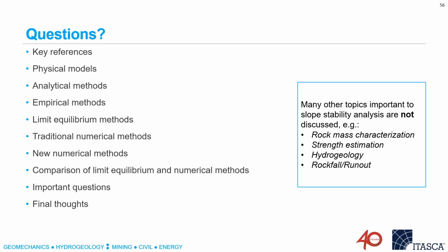And early work from Everett suggests that it should be applied only to blasting, and even some of his later work, most recent, he's again trying to tackle this and saying, well, it should only be applied to blast damage. But we know that there is damage due to stress relaxation that occurs, and it extends deeper than just what you would get from looking at blasts.